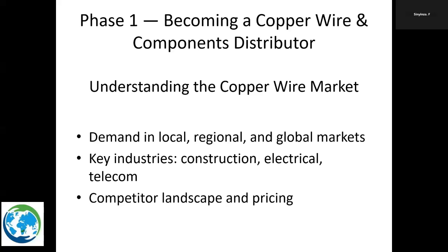Because those that have got copper, it's being used in electric vehicles, it's being used in phones, it's being used almost in all electronic gadgets as a metal on its own or as an alloy. So it is used in combination with other metals. I can briefly talk about brasses and bronzes, because for brass, you add the zinc, you add the lead. For bronze, you add the tin, okay, and a bit of phosphorus if you want.